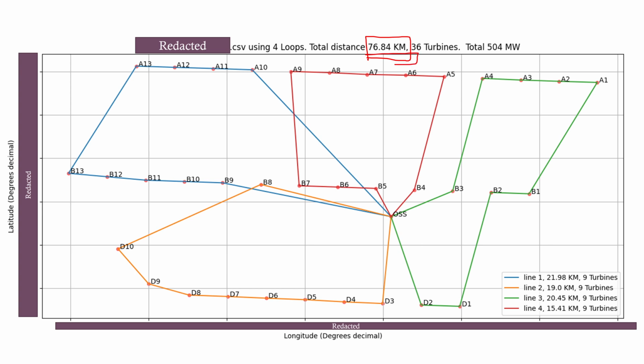And that is why you may say, well, this is just cable length. It doesn't take any account of the actual cross-sectional area of the cable. So although I need an extra 20 kilometers of cable, if I only use a very small cross-sectional area just for back feeding the turbines in the event of failure, then the cost might not be that much. But if you want to actually export anything significant through that interlinked loop, then you are looking at a reasonable amount of extra cost. And this is what accountants see when they do this.